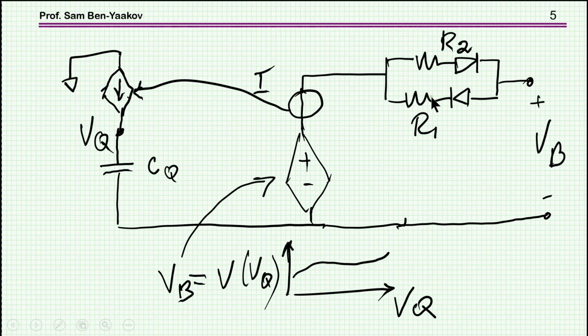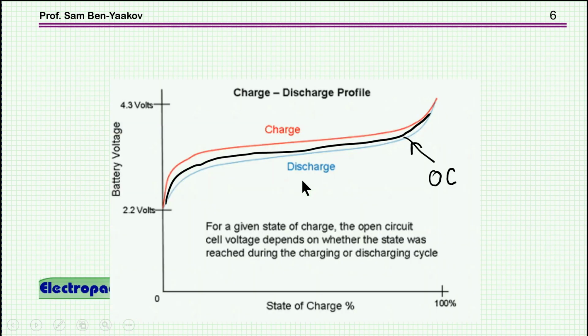And then we have here two resistors, one for the voltage drop during charging. So the voltage, this is the terminal of the battery, the terminal. So the voltage here will be higher than the inherent battery voltage during charging. And then we have a discharge resistor, so that the voltage here will be lower than the inherent battery voltage. So from this curve, for the given current, I can estimate the resistor here. I did it in a very simple, intuitive way, just assumed values, and I didn't actually calibrate the model I'm going to show very accurately or very carefully. It is just a way of showing the idea, and obviously if you have the charge and discharge for different currents, then you can do a much better calibration of the model.